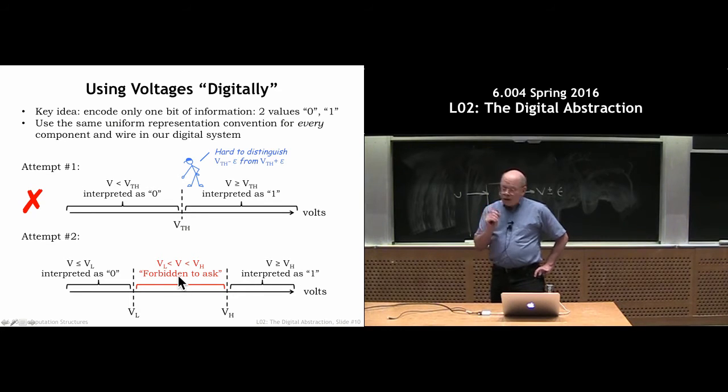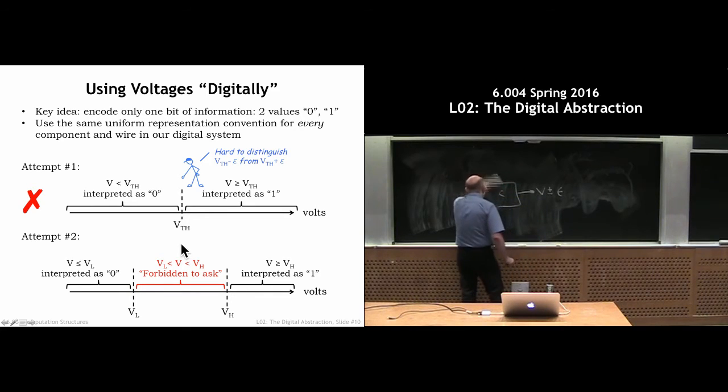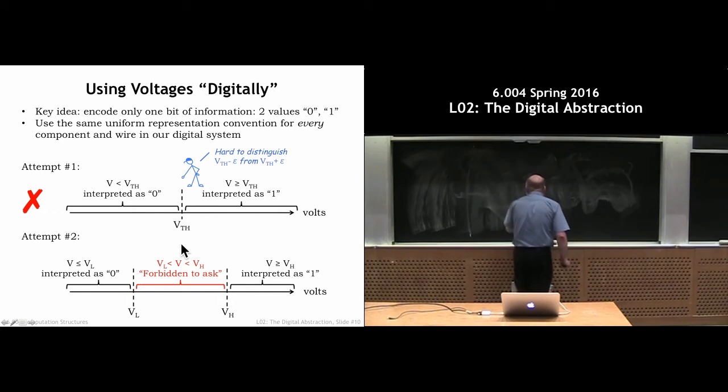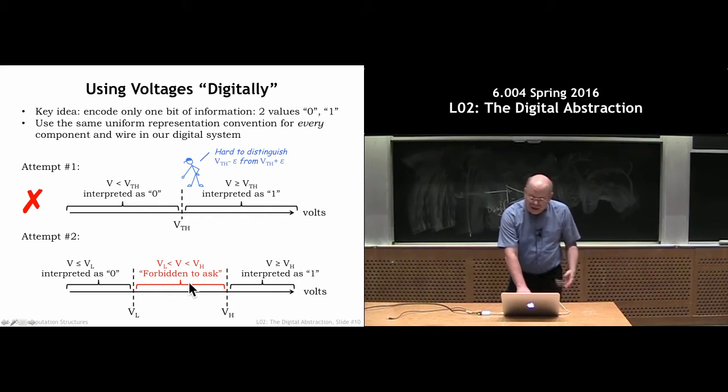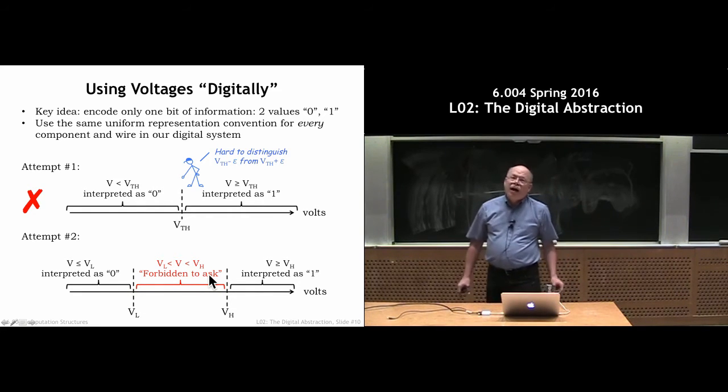So what I'm going to do is build a fairly crude device. It does have a single threshold. Suppose I built myself a little op amp. Voltage comes in here. There's a voltage divider here that helps me detect a particular threshold voltage. These are cheap resistors, so exactly what V sub TH is, I don't know, but it is somewhere in the forbidden range. It could be here, it could be there, it depends what device I buy, it doesn't really matter.